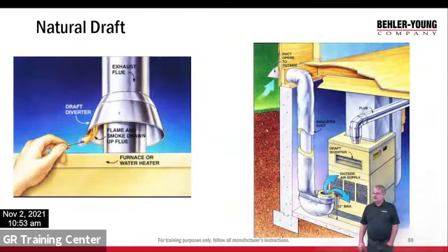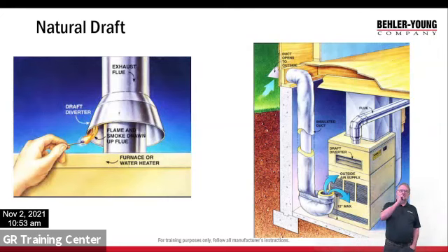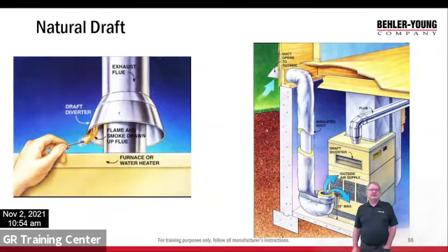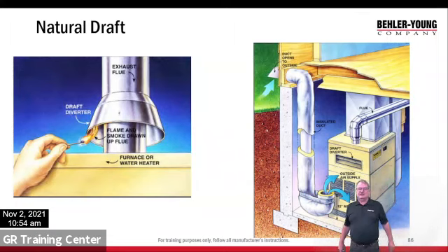Okay, natural draft. We kind of talked about this a little bit earlier. If you look at that on the left there, again, they've got a gentleman holding the match to the draft diverter. If the chimney is correct, it will actually pull the smoke straight up. You can feel the draft. That's one of the tests we used to do. Back then, actually, we'd use a cigarette because we could smoke and everybody did. But you have a draft.